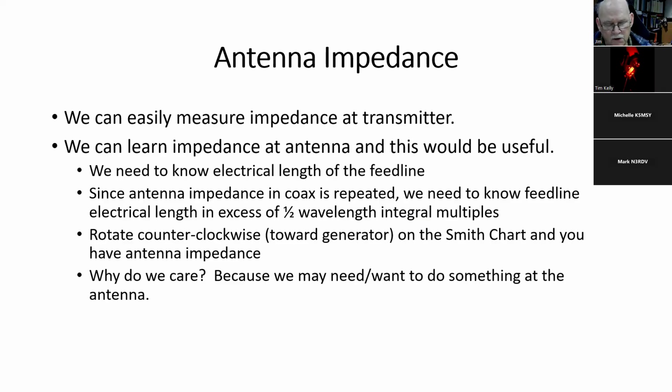But you can also use a Rig Expert or a network analyzer or a nano VNA, any of these cheap devices, and you set the velocity factor equal to 1 and measure the length, and that's the electrical length. And that's what we care about. We don't care about the physical length. If we're going to get into attenuation and loss, well, we care about the physical length, but for the purposes of matching impedances, what we care about is the electrical length.